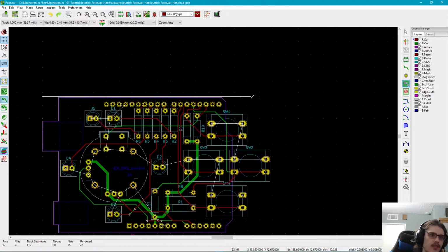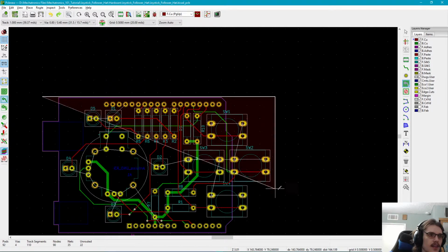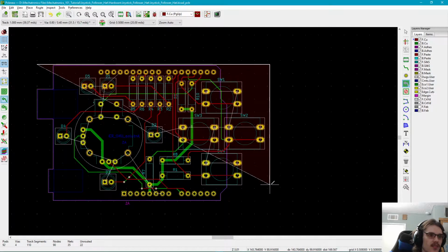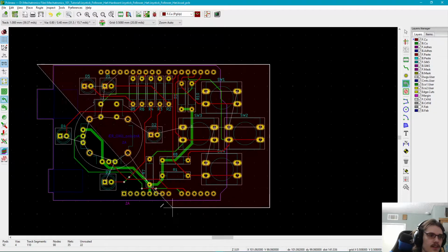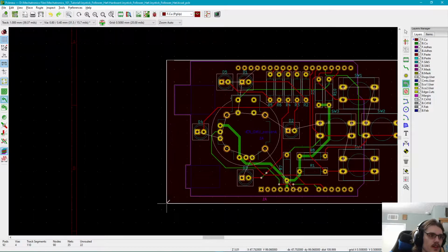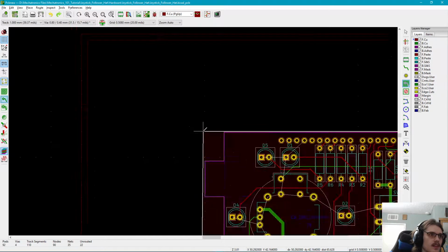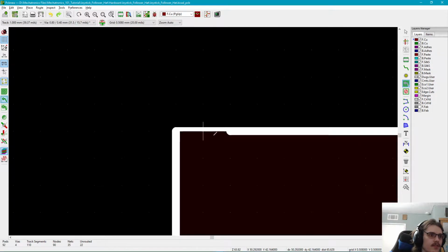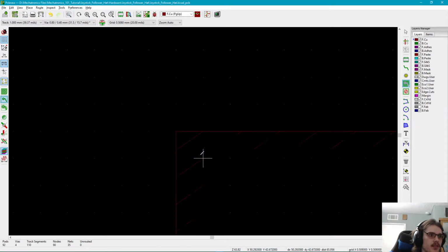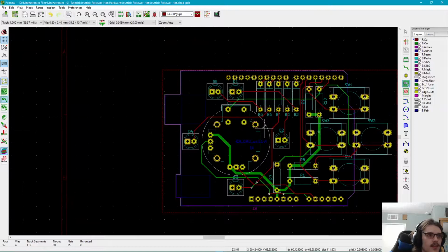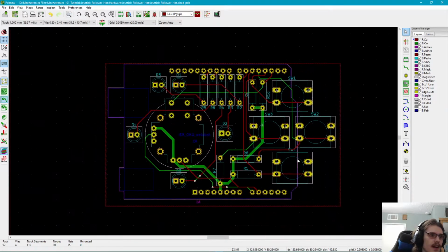So this is how I get straight lines and kind of just eyeball it off the bat. So I hold Control, then I left click, and then I now have to break this side, so I hold Control again, so that's nice and even. Then I left click, hold Control again, and then I left click, and finally I usually zoom into this side, hold Control, left click, and then hit Close Zone Outline. And just like that, we have our first outline.